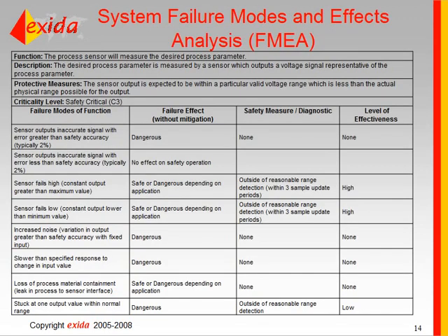All right, so the next step after the system design is to do what we call a failure modes and effects analysis at the system level. What you're essentially doing is looking at the individual components that have been documented in the system design and trying to figure out how they can fail, and trying to make sure that you have ways to detect that failure built into your design.